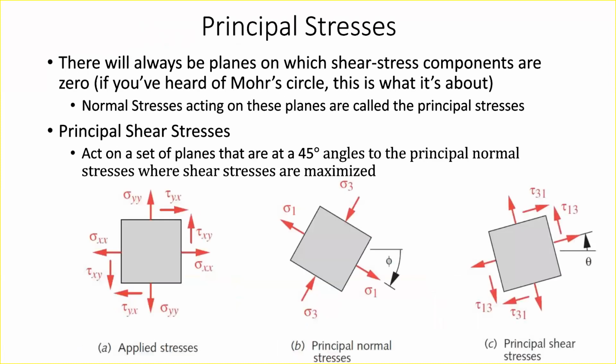So with these principal stresses, the idea is that if I have these combinations of normal loads and shear loads and I rotate my frame of reference, there's a proof that says I can reduce all of these loads into 2 loads in plane in this case, or 3 in general if you're in 3D.